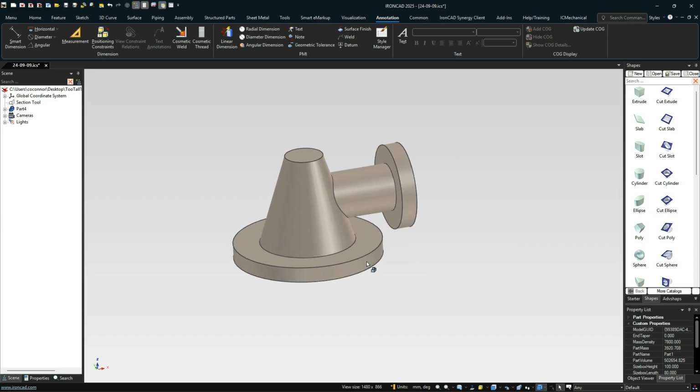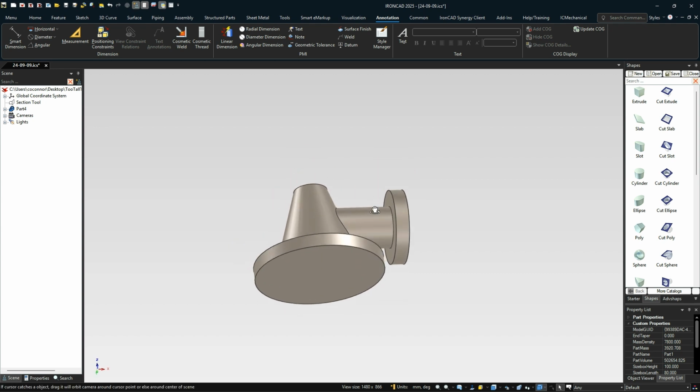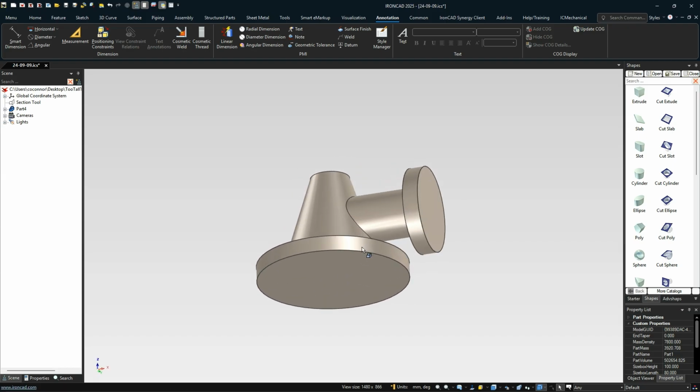Next, we're going to go ahead and just do the extrudes on the bottom. We're going to actually shell this first before we do the extrudes on the bottom and the side. We can do them either way because they're going fully through, and same for the holes, but let's go ahead and just do this thickness information here. So the way we're going to do this is with the shell feature.